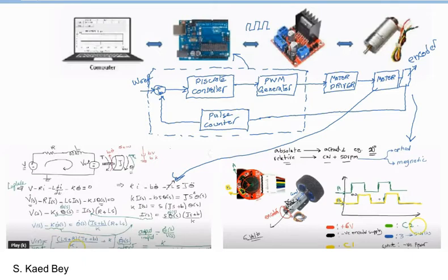We will be able as well to determine from the speed of the pulses the angular speed of the motor, and hence we use this information back in the Arduino in order to improve the PWM duty cycle, which will be fed to the motor again in order to maintain the desired angular speed.